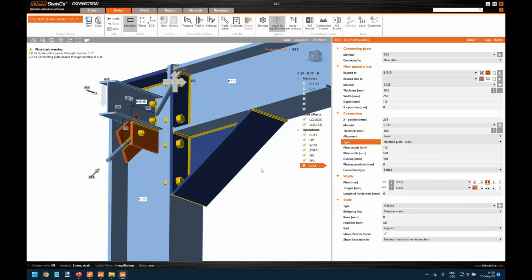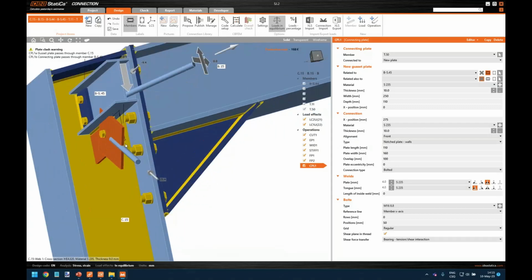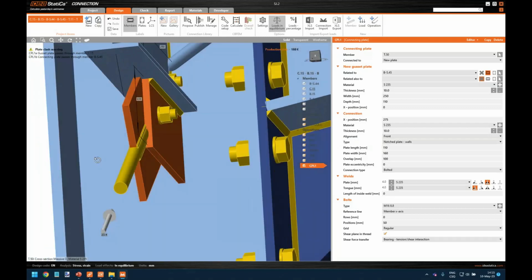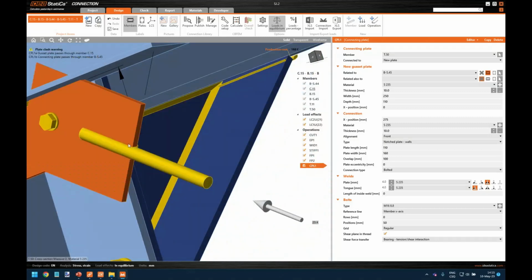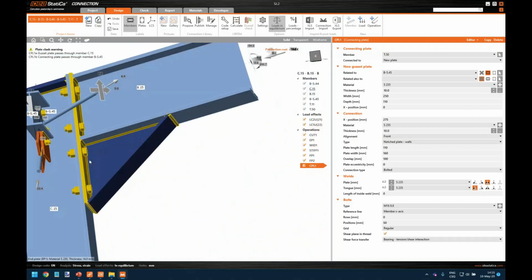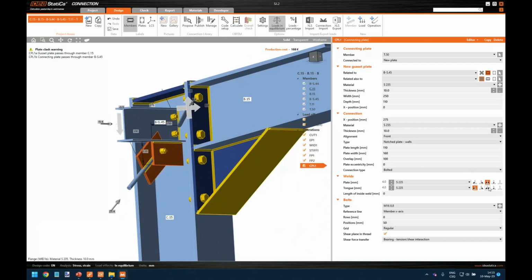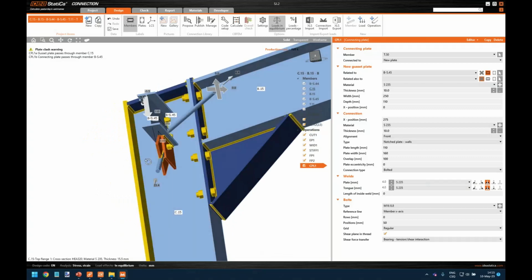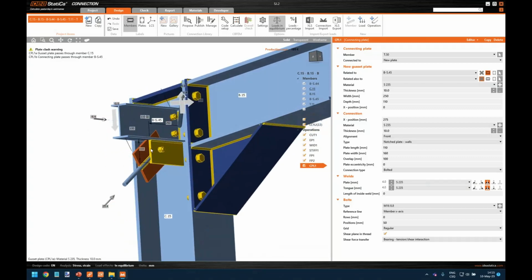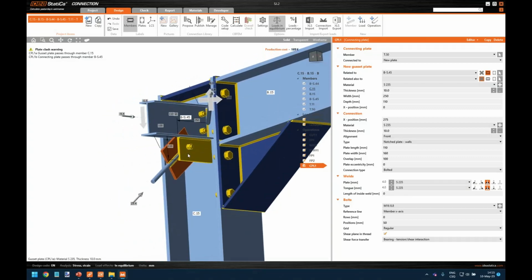So if I go here for this connection, notched plate walls, this means the wind bracing is now welded into a plate with a hole for the wind bracing. Yeah, I can switch the welds to be on both sides. This is a better design for me, and now I can start shaping the connection.